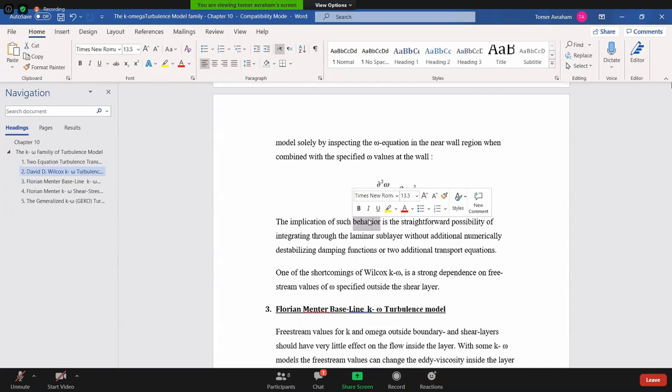But as Spalart said and assumed, the problem with large eddy simulation is the near-wall area. When we use large eddy simulation, the area near the wall where we have solid boundaries is probably 95% of the mesh.